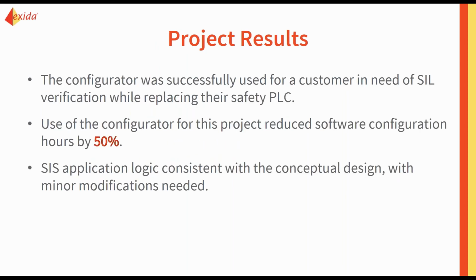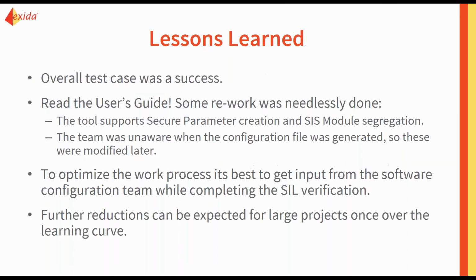First of all, it was successful. The safety logic was generated from the SIL verification and design SRS file. And so they were able to use this while replacing their safety PLC. It actually cut down the time to configure the safety logic by 50%. So that's a significant cut. And then, of course, the safety logic was consistent with the conceptual design, with a few minor modifications needed, as we said. So what are the lessons learned?